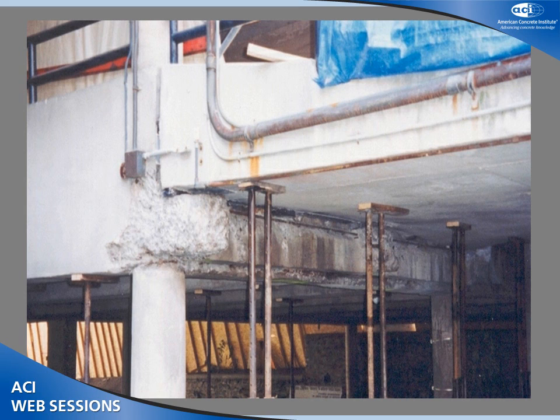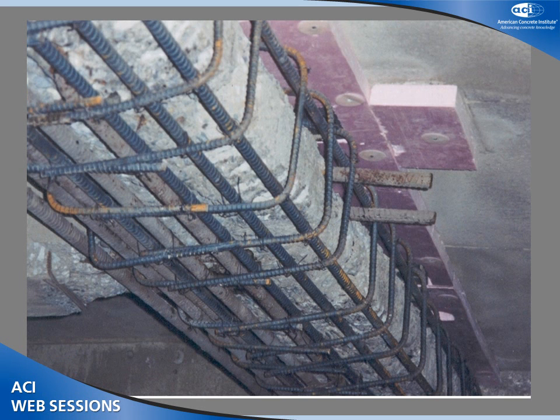An element like this, at the entrance of a parking garage, is subjected to a lot of de-icing salt, scaling, and corrosion of reinforcement at the joint, which was leaking. This is very typical damage. Normally you would remove all the contaminated concrete, and then you would use shotcrete, in some cases fiber-reinforced shotcrete. In this case, we tried a number of different shotcretes, but also a new technology that was self-consolidating concrete.